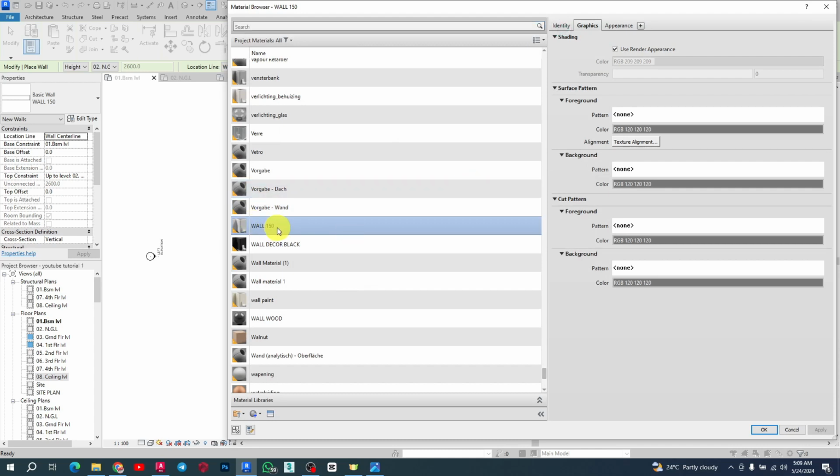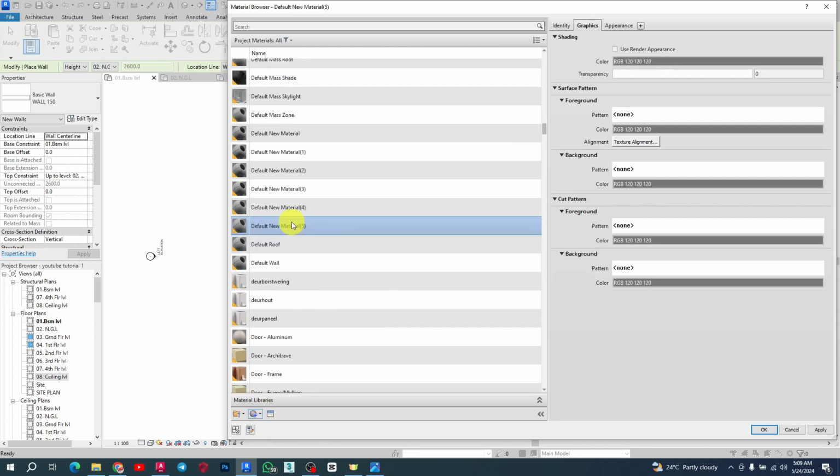So click on that arrow, right click, and then you say duplicate asset. If you don't want to go down that road, you can always add another material. So you click and add new material. So let me start with a predefined material that I already have, or I can just click here and say create new material. So this is a new material that comes on right now. You always have to rename it. So I'm going to call it basement wall or BS wall, right?